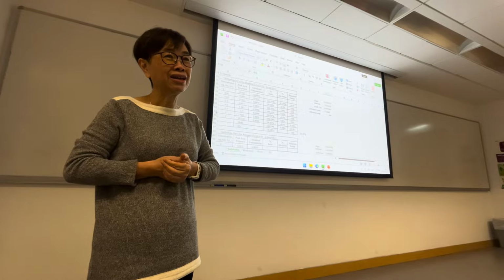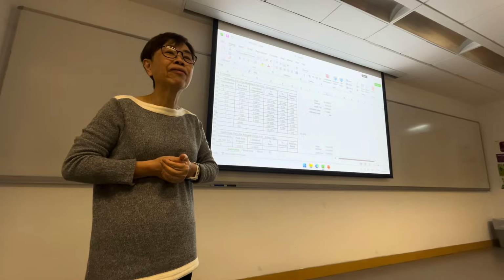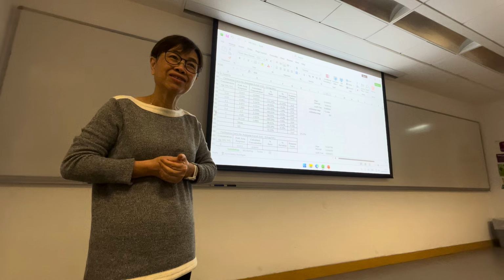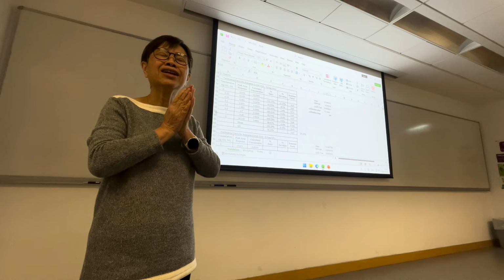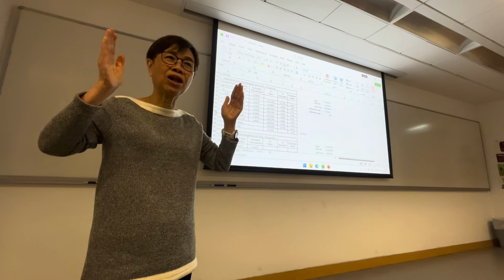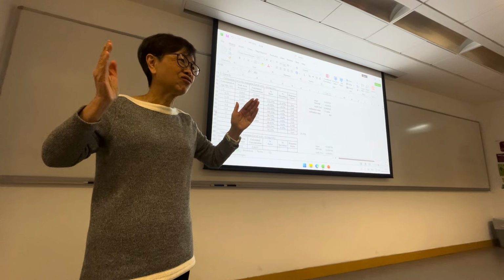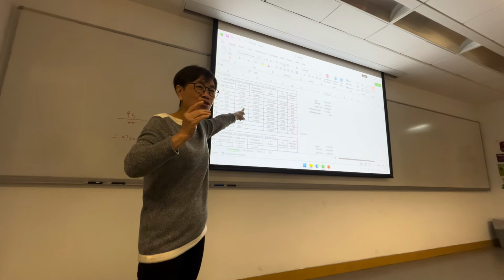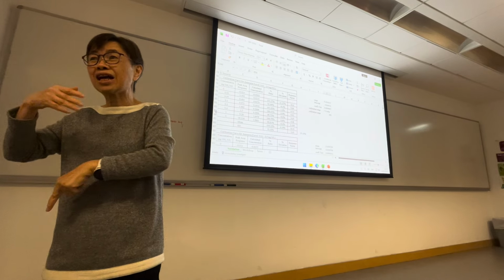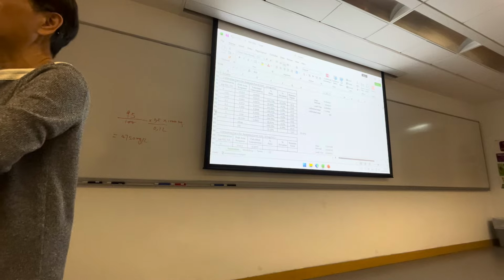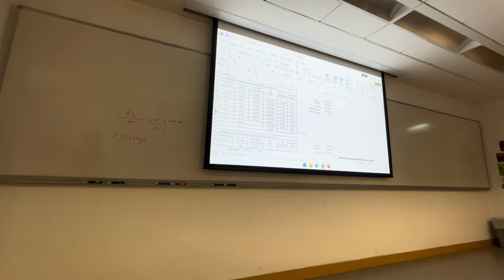0.01 to 10, that is a 1,000-fold range. There is no instrument whose linearity can cover such a large range without good correlation. Okay? So that is how you comment on the calibration curve, and also whether the spacing of the calibration curve is good enough.